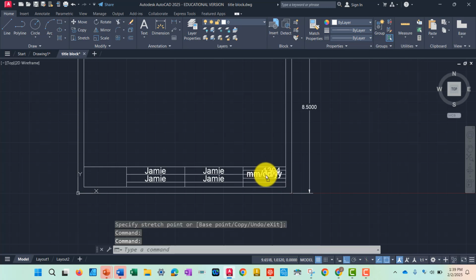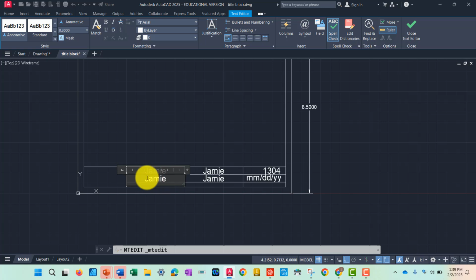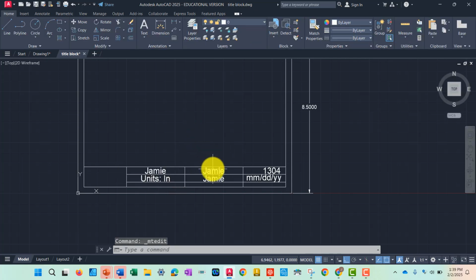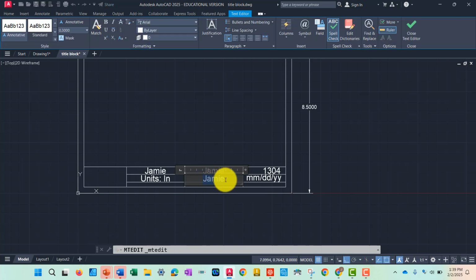default. A lot of companies will already have this set up for you so that you can just start using their templates with all of their settings. Generally, you'll have things like, is this in inches? Is it in centimeters, meters? We'll use view base when we get into the 3D commands. The very first ortho view that you put is usually how you define that scale.